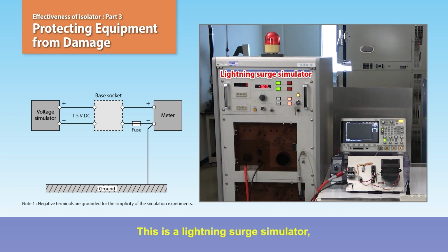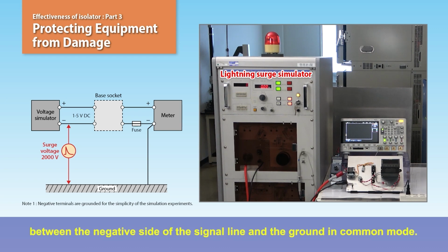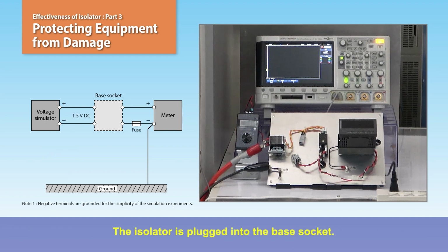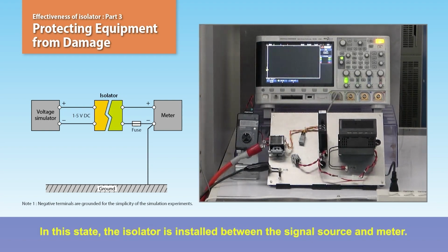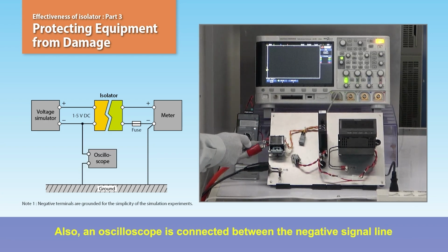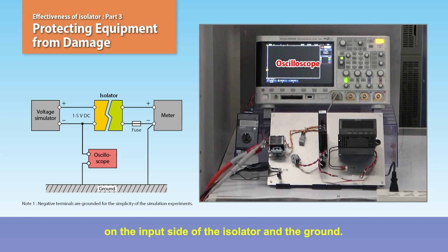This is a lightning surge simulator, which is a device capable of applying a surge voltage of 2000 volts between the negative side of the signal line and the ground in common mode. The isolator is plugged into the base socket. In this state, the isolator is installed between the signal source and meter. Also, an oscilloscope is connected between the negative signal line on the input side of the isolator and the ground.